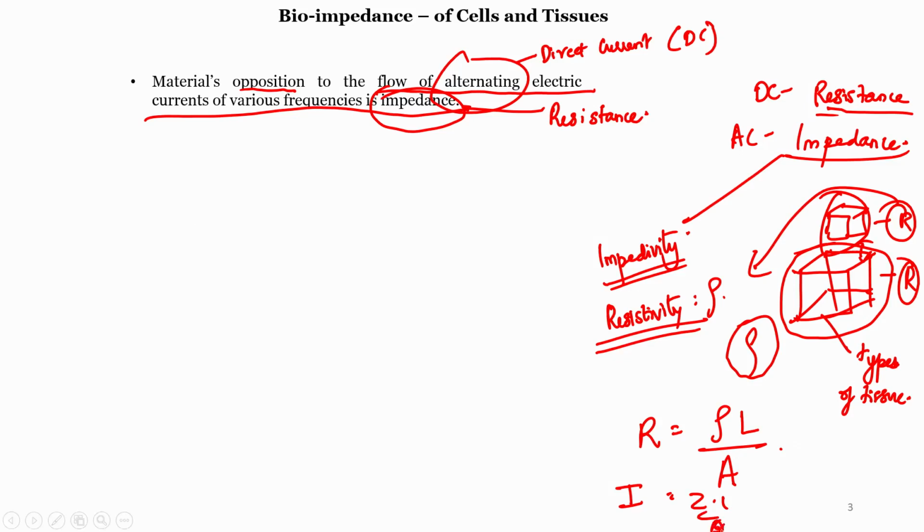We need to actually separate out the imaginary and real parts of the impedance and then do the impedivity calculation. Otherwise, by default impedivity will be a complex quantity, because as you know there is phase information involved, and capacitance and inductance effects will be there.